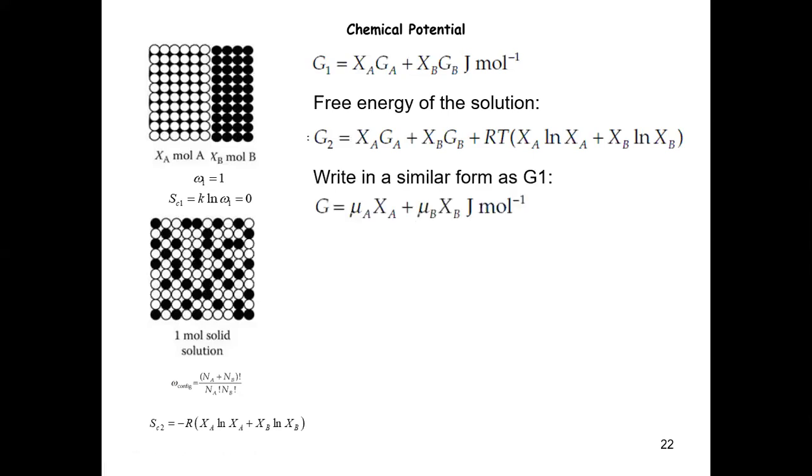And one thing we briefly mentioned at the end of the last lecture is that, inspired by this very simple form, if you have a system, you can write it as a molar fraction times the so-called molar free energy. This is a very simple linear term that gives you an intuitive understanding of how you can express the free energy. For the solid solution case, we end up with this relatively lengthy expression. Now we're asking the question: can we write the free energy for the solid solution state in a similar form as this simple combination of the molar free energy times the molar fraction? The answer is yes.